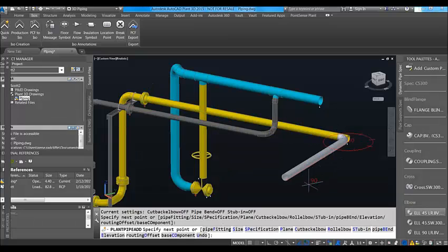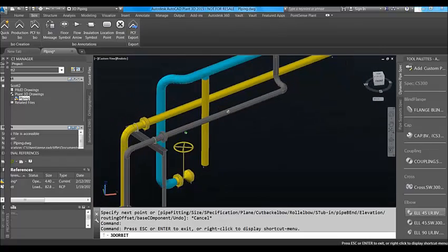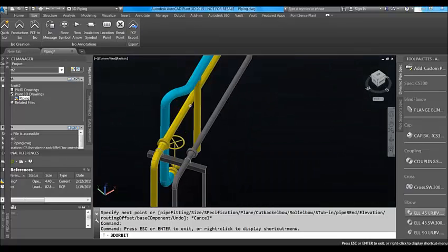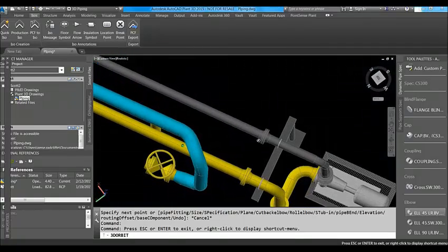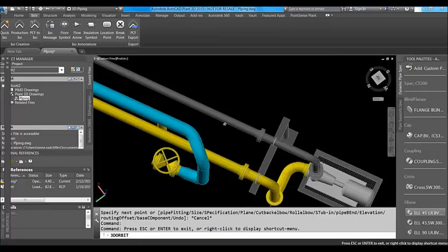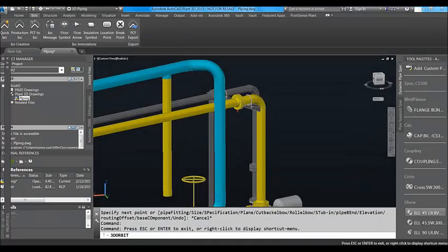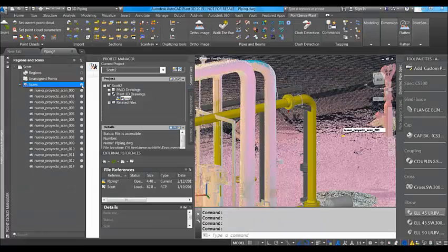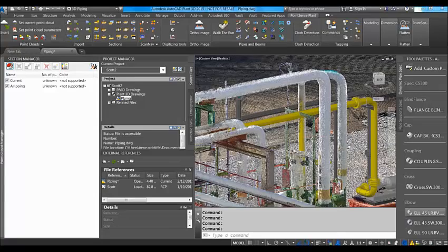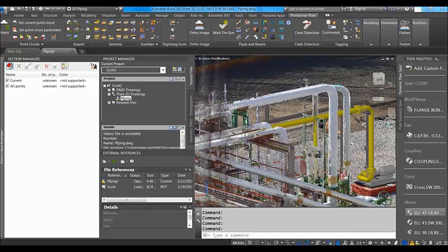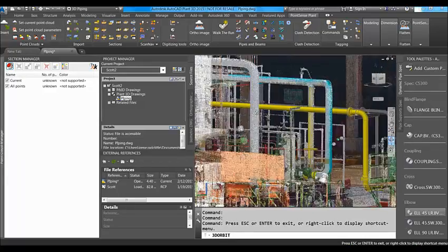Let's continue this line on here and take a look. So we can determine what we were going to actually create here. Traditionally, when you're as-builting with modeling in solids, you can see exactly where the clashes are. By taking that yellow line through there, we can determine by seeing where it hits that solid vertical run that there's a clash. Typically, you would have to have actually modeled that solid to see that clash. Now with the advent of the point cloud in AutoCAD, just by turning that point cloud on, we can rotate our whole model around and see exactly how that's going to fit in with the existing plant.